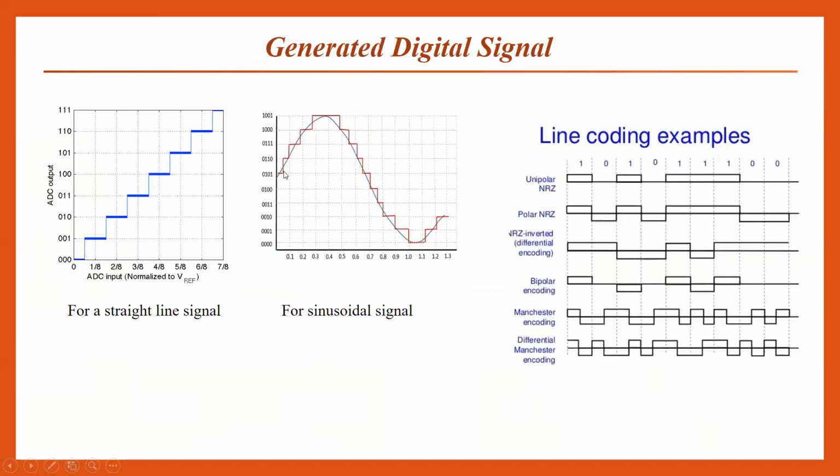The bit sequence assigned to a particular sample of the signal is presented here according to the quantization level. This was the quantization level 5 volt. Then this bit sequence is provided to this sample, and thereafter for this sample this bit sequence is provided. This was the digital form of our transmitted signal, and this signal is in logical form 1010.